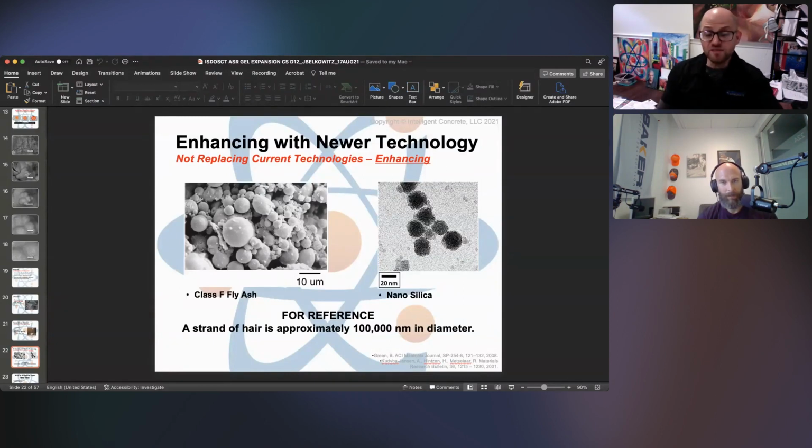And to the right of it is this nanosilica-sized particle in a colloidal dispersion. So colloidal suspension, we call it colloidal silica. Milk is a colloidal suspension of fats and proteins. So it's got to be a universal suspension that either happens naturally or we manufacture it that way to keep something in suspension that normally would not stay in suspension. Now, that can be anything, but for our intents and purposes, it's nanosilica-sized particles. Does that make sense?